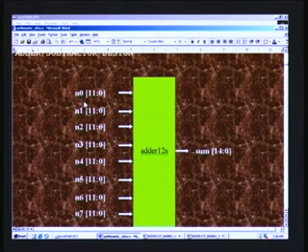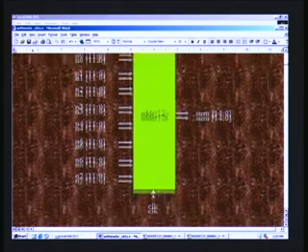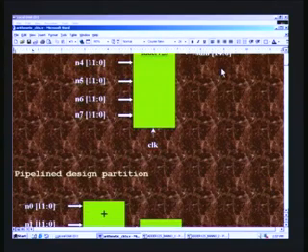There are N0 through N7, that means you need 3 bits. If you are to add 2 numbers at a time, you naturally need 2 to the power of 3, which is 8, and 3 is the number of bits we had to add, because those 3 bits are causing this addition. We will explain this a little more clearly later on. As a result, whatever is 12 bits here will grow by 3 bits, and hence the result will be 15 bits, and that is its pipeline, therefore there is a clock here.